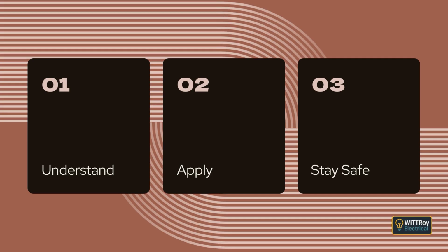Clause 3.9.9.3 Penetration of fire barriers. Where wiring passes through floors, walls, or other fire-rated elements, the penetration must meet strict requirements. The opening must fit closely around the wiring system, the size of the opening must be limited, and the fire rating of the structure must be reinstated after the wiring is installed.